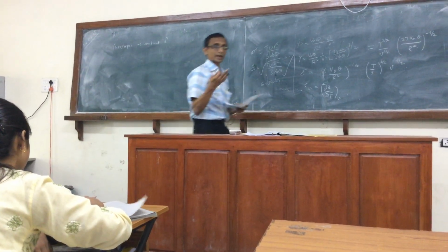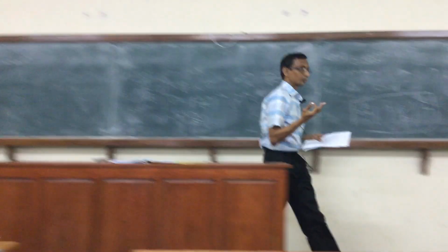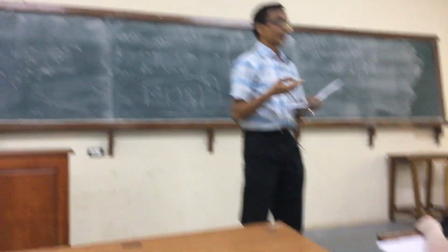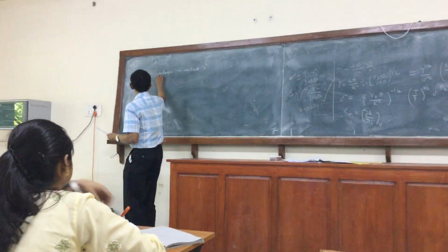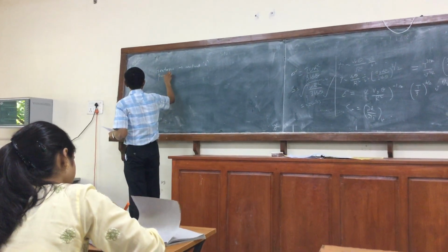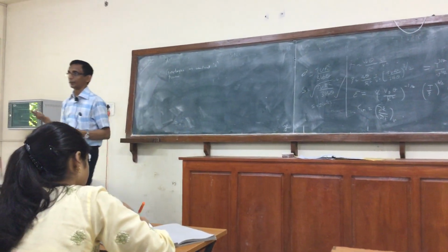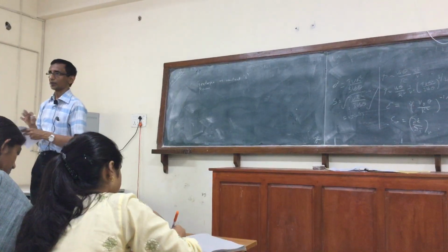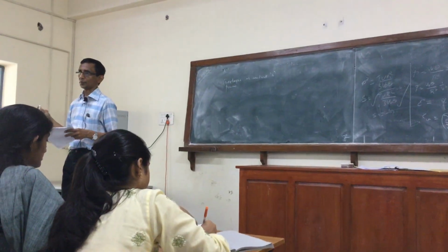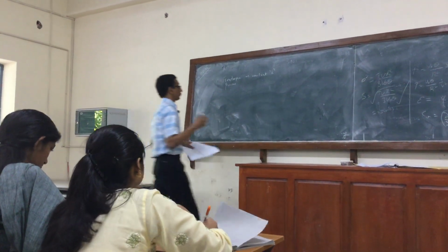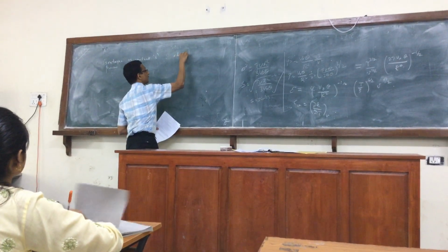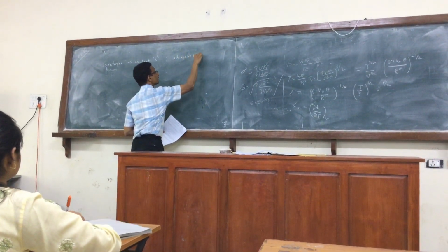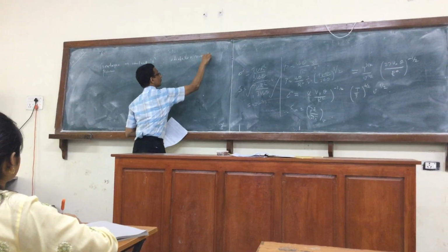You should know what isentropic means, first of all. It's a constant entropy process. That means throughout the process, the entropy of the fluid remains the same. If you have a fixed mass of fluid, that means the specific entropy remains the same. Take one example where this occurs in the process: adiabatic plus reversible.